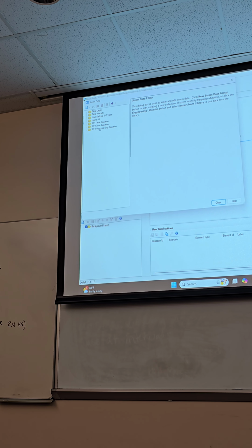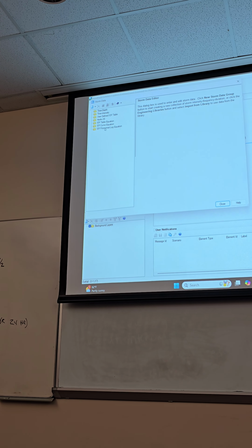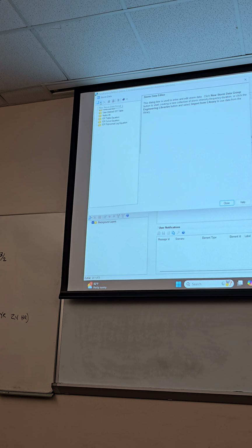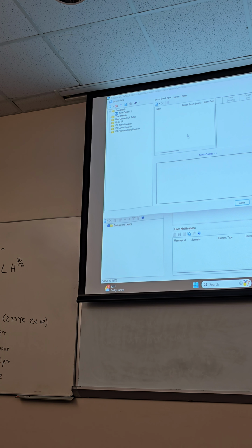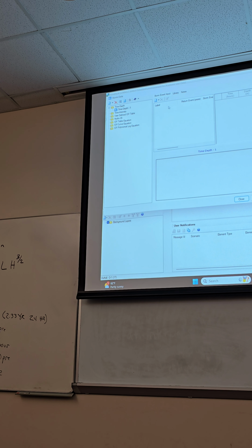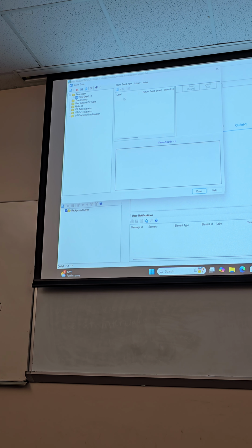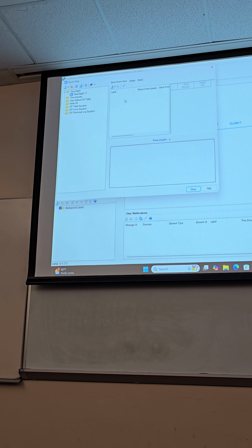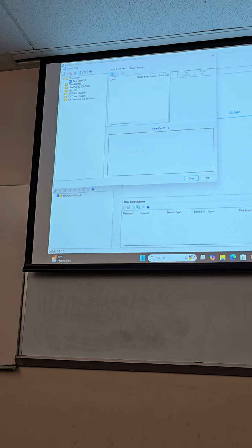So we could do a time depth, intensity, IDF curves, we can do equations, we got a lot of choices. But up here, under this little white piece of paper, we're gonna do time depth. And this time depth is going to be the distribution of the depth of rainfall over the 24 hours.